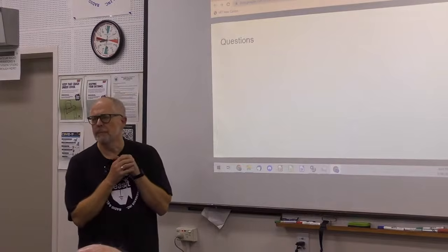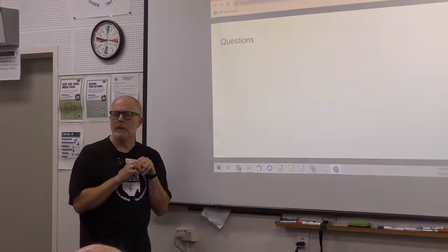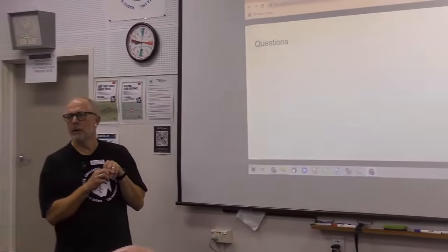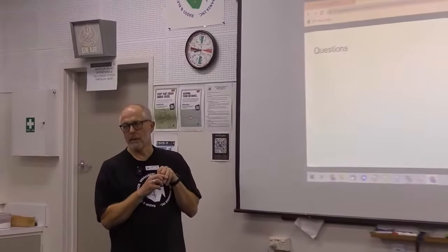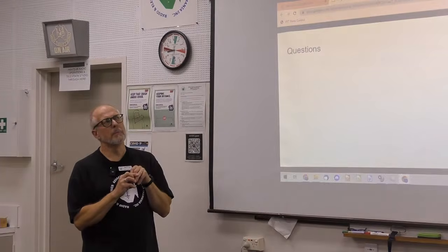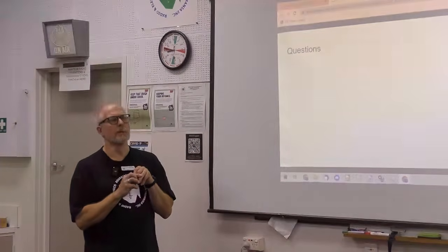Yeah. So to comment from personal experience, I have used a magnetic loop where the resonant frequency, which is what you're tuning with the capacitor, was not the lowest SWR point. That was some distance away because of the way the thing had been constructed. Yep. So the position of the coupling loop affects your impedance, but the capacitor affects your resonant frequency. Yeah. Okay. Cool. Thanks, Steve.